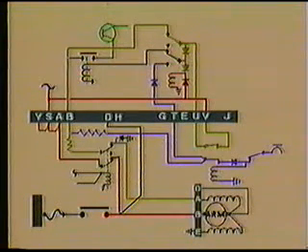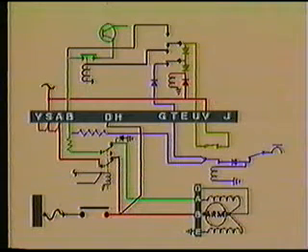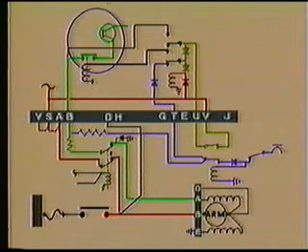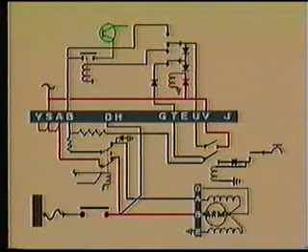As this output flow increases, it will reach a point so that the control panel reset relay will energize. As it energizes, sufficient power will flow through the closed contacts of the relay to energize or reset the trip relay and move it to the closed position. The regulator circuit is now connected to the A lead and will begin controlling the generator output. However, if either the auto line contactor circuit or the generator feeder fault circuit sense abnormalities in the system, they will again open the trip relay and stop the generator's output.